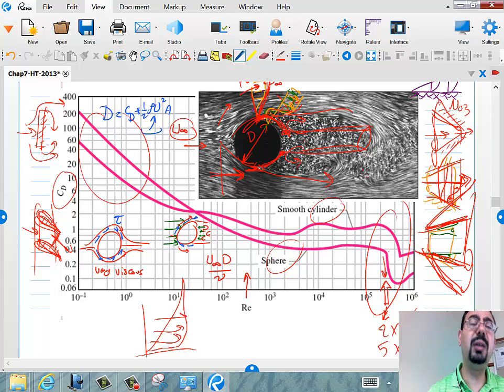And so what happens over here is the very viscous flow. This is for very small Reynolds number. If the Reynolds number is that small, like 10 and 1 and 0.1, that's basically like throwing a cylinder into honey. And the flow is very, very viscous. Right? There is no wake. As a matter of fact, in this region, the flow will look like this. Look at this. The flow is basically just sticking to the wall all over it. And so this is mainly skin friction drag. There is no wake, there is no pressure drag.